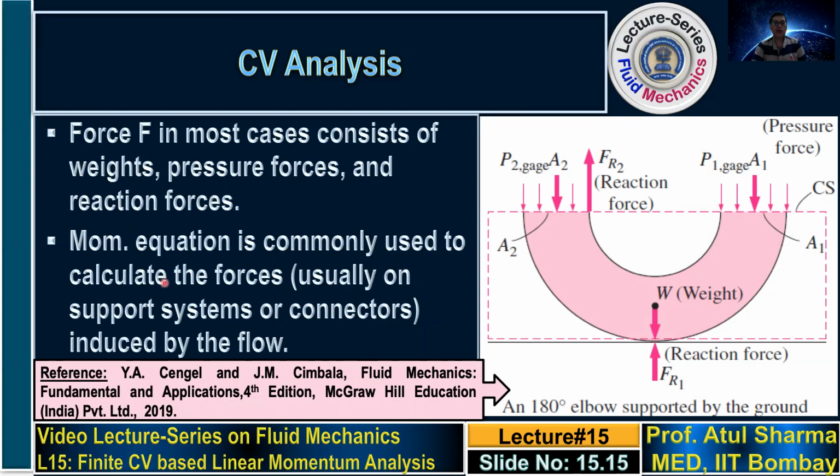The momentum equation is commonly used to calculate the forces, usually on support systems or connectors. As I had shown, a tripod is a support system, and the elbow that I showed you is a connector, where the pipeline is connected to a water tap through nuts and bolts. So this momentum analysis that we do mostly is to calculate the forces corresponding to support systems or connectors, where mainly the change in the direction of the flow leads to certain forces which need to be supported.